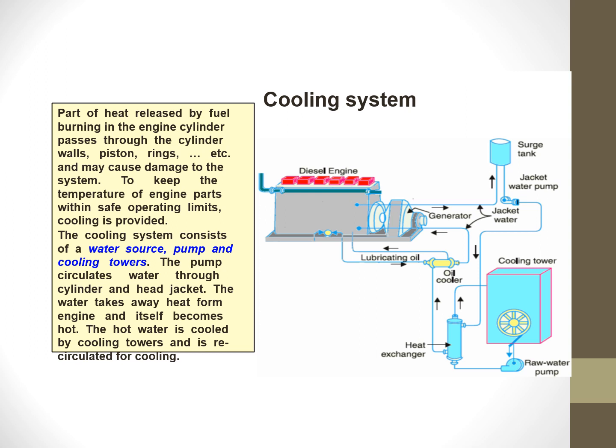The heat released, that is what they are saying is the heat balance sheet. If you are doing the heat balance sheet for a diesel engine, 25% of the heat is lost to the surroundings, to the cooling. The efficiency of the diesel power plant will be around 30%. Nearly 70% is going as waste. The cooling water absorbs nearly 25% of the heat generated inside the cylinder. It is mandatory, even though it is wastage, but it is mandatory.